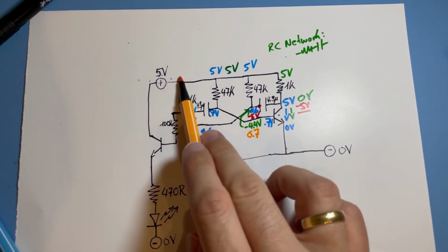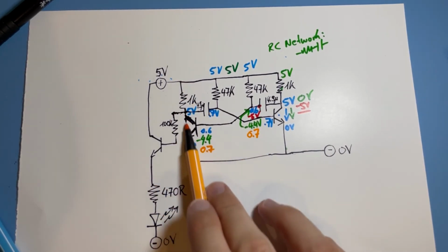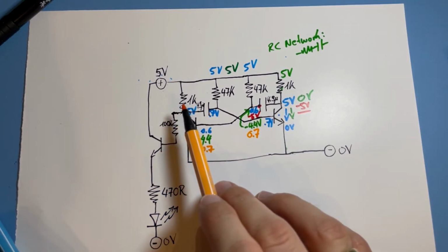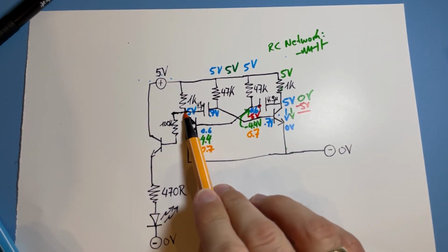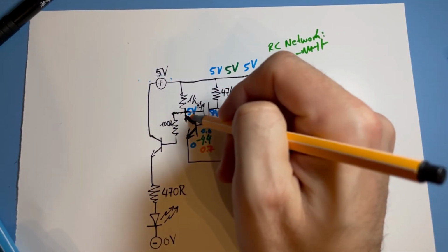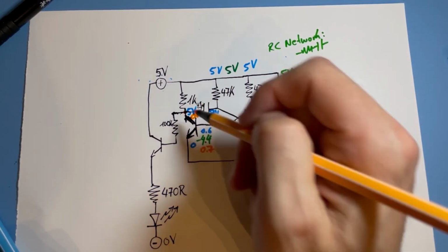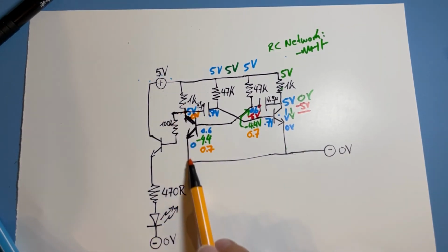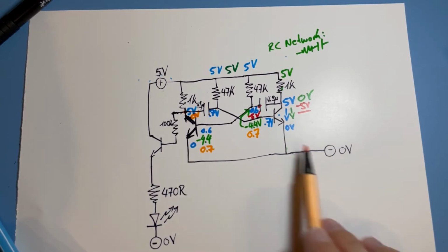And this transistor starts conducting, then there is a voltage drop of 5 volt here to then 0 volt here. Let's write that down, 0 volt at this junction here.